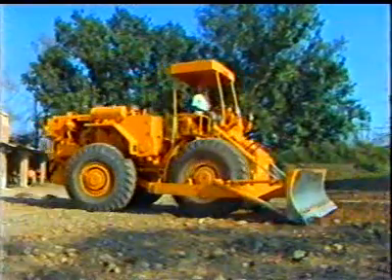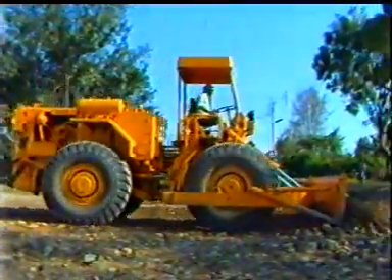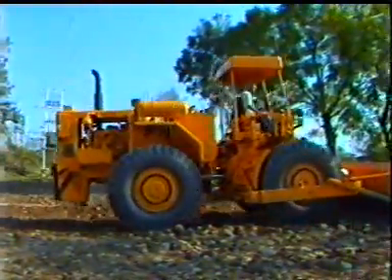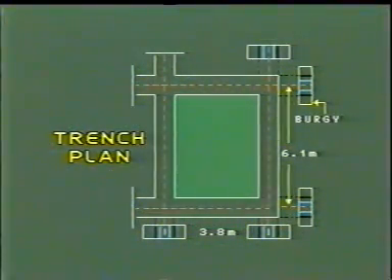Layout and construction of burjis. For starting any construction, the site is cleared either manually or using mechanical earth movers. After clearing the site, the exact position of the foundation trenches is marked on the ground. The graphic shows the foundation trench layout plan along with the location of burjis.